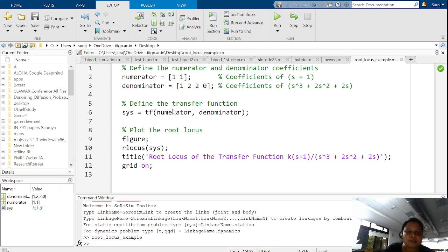Okay. So it was some sort of this. So there were poles: a pole is at origin, a pole is at -1 plus j, a pole is at -1 minus j, and a zero is at -1. So you see, it went outside along the asymptotes at angles of plus and minus 90 degrees, and one of the poles converged to the zero.